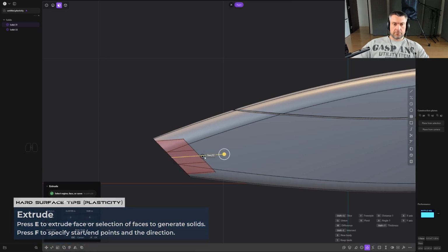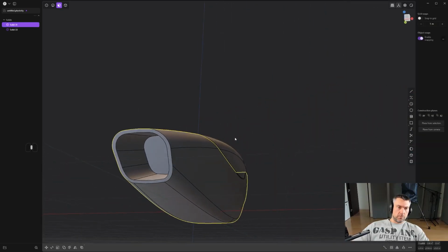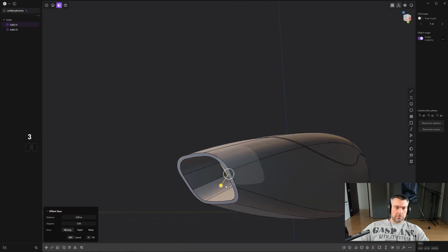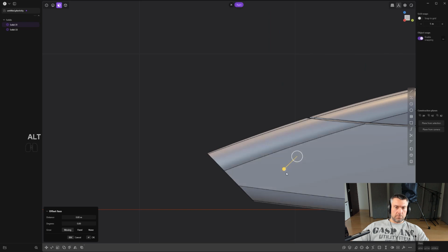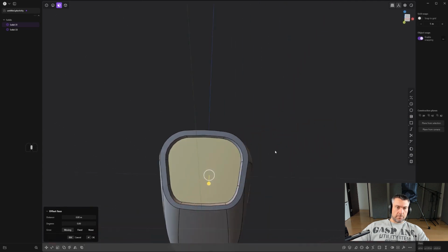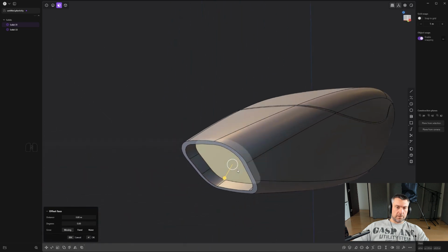And you drag. And you can actually see where this extrusion is going. So we could go along this line. So you could press tab, shift here and sort of run along the line like this and right click, and it's going to go in, but it's not going to go at a weird angle. Now this is a bit too deep, so we're probably going to move it back a bit. So let's just move it back a little bit like that. That's cool. In fact, what we could do is we could scale this, but I think it's going to be fine.